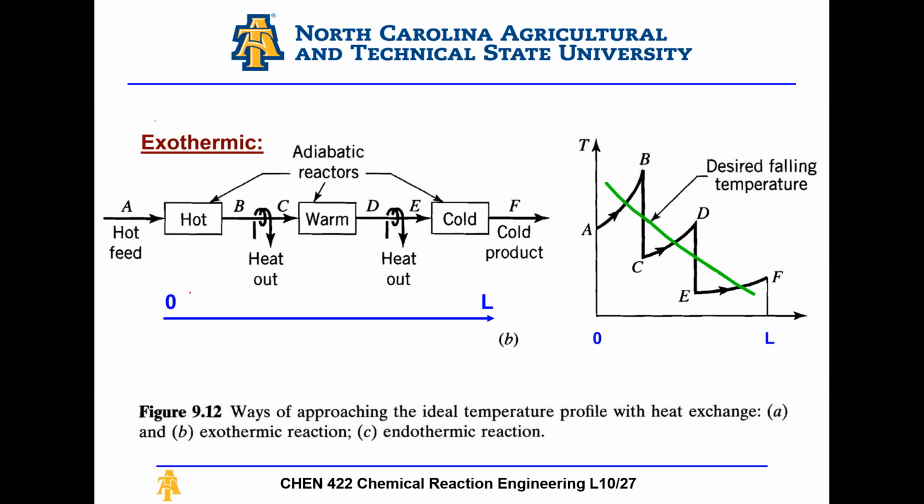And this scenario is called multi-stage operation with interstage cooling, right? So I'm operating 3 reactors at 3 different temperatures. I have cooling between them, and this is fairly common actually, especially when you have gas phase reactions.